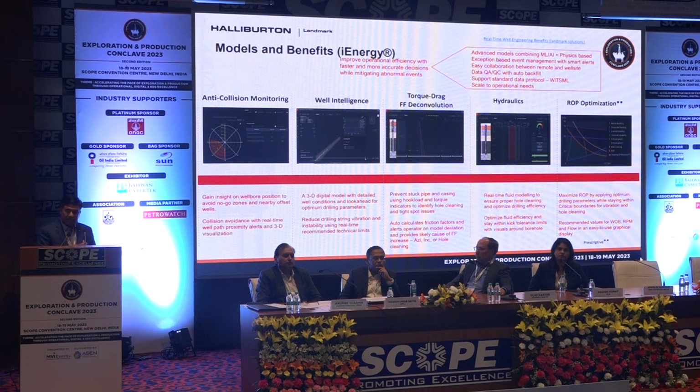So we always have a problem in the industry while drilling. You get cracks in the tools or fatigue, or you get twist-offs in the motors, or you get some major dents happening on the RSS when we are rotating at a very high speed. So this model will give you the safe drilling window. It will enhance your drilling stability so that you can save everything right from the bit to the top drive.